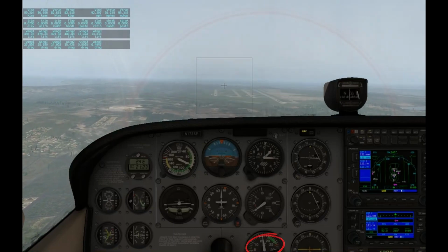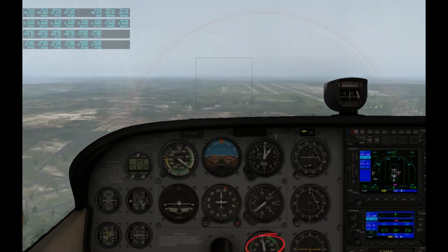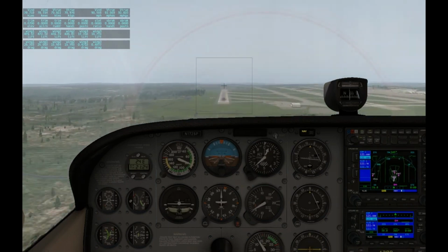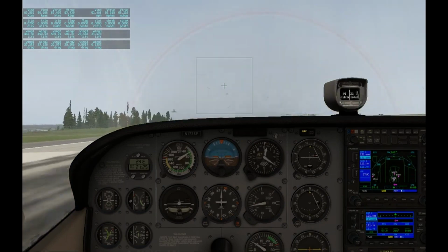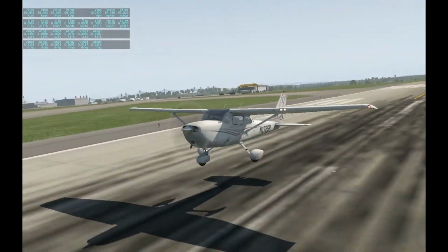We are on the final approach path, and for this approach we will not be utilising flaps and will be depending solely on the throttle control. So we have now set our engine RPM to 1600 RPM, and by monitoring the PAPI system, also known as the Precision Approach Path Indicator, we can land the plane perfectly at the right touchdown zone.